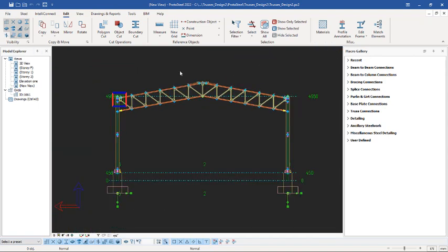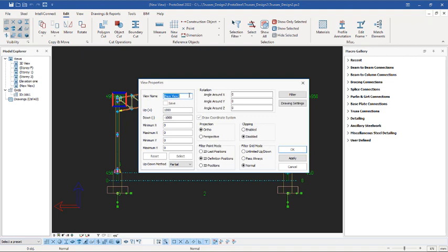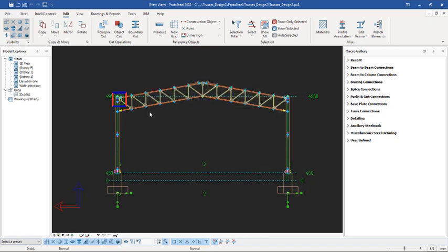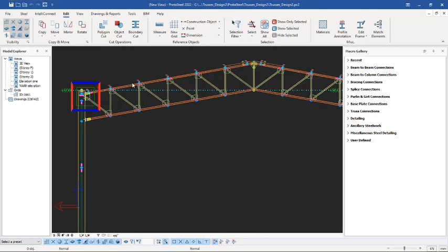Okay, just like this. So with this, just double click right there, and then you write it as the width elevations. Okay, so you can just put it as the width elevations right there. Width elevation, just like this. Let's make this a capital letter like this. All right, so after we click on apply right here, it will reflect here. All right, click on the OK option, just like this. So we have gotten these elevations now.